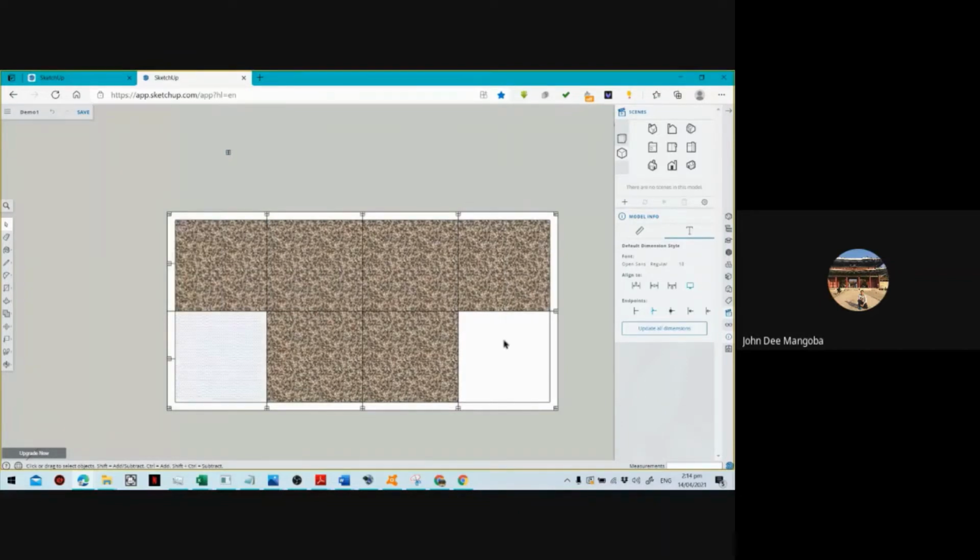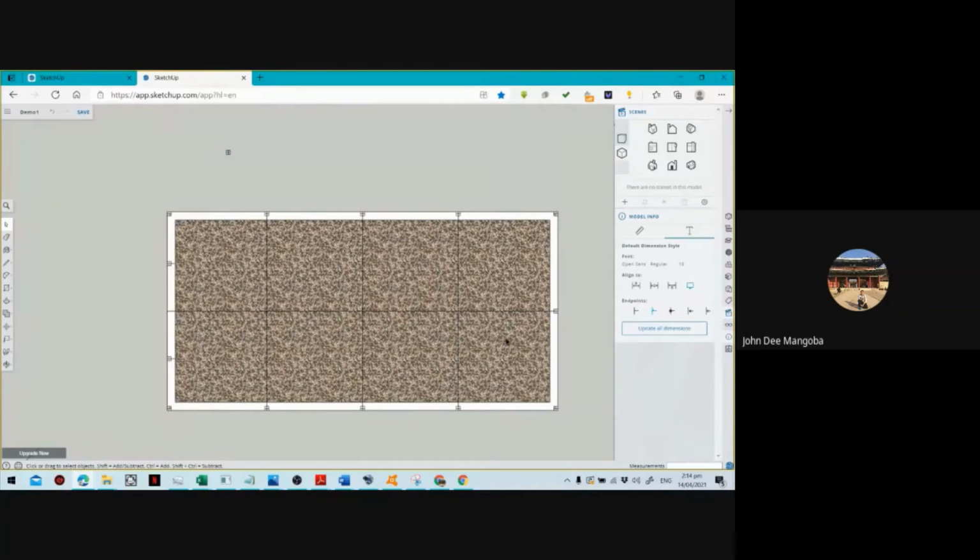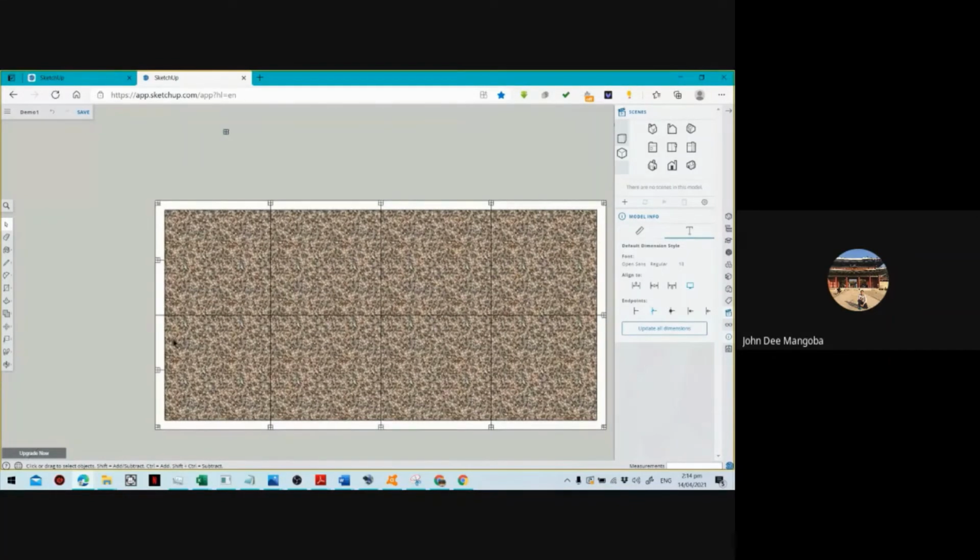Okay. Every time we have a closed surface, SketchUp makes another layer. That's why you see that. For these lines, we won't be needing them also. So I can just remove them. Or as mentioned by Rodrigo before, instead of deleting them, we can just use hide. For the remaining, what I'll do is hide them instead of remove.